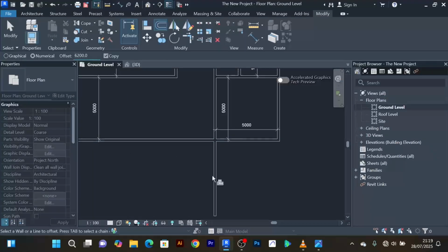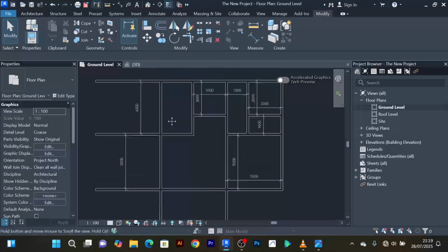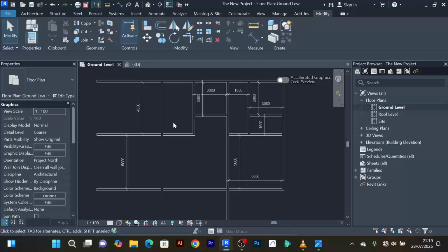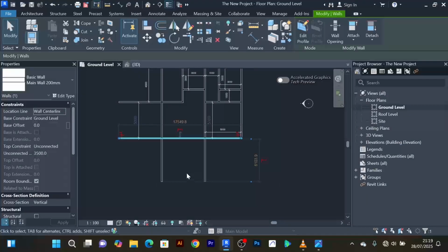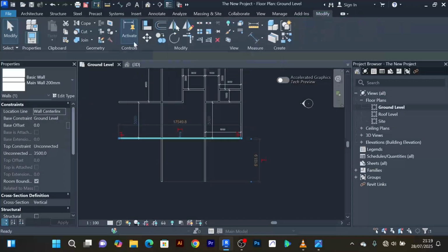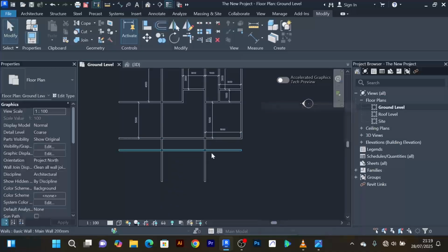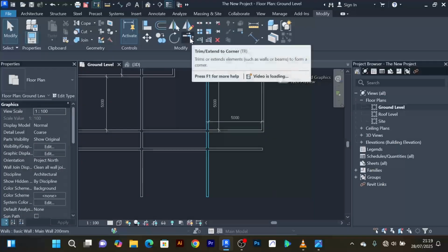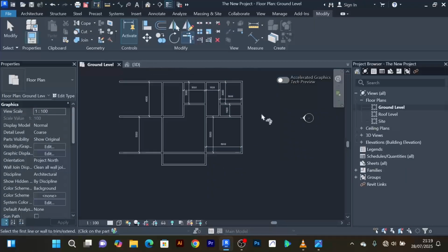6.2, like that. Then I can offset it here just like that, but of course it is not going to extend all the way to that side. For now let me leave it there, and I'll extend this one a little bit outside by offsetting it at maybe 1.7. That will give us 1.5, just like that. Then of course I'll come to my trim. I'll trim this to this, I'll trim this to that, just like that.